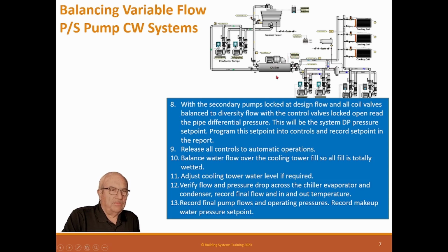And also, more than likely, you're going to have to come out early on the job and set the water through the bundles, because the chiller manufacturer won't start this chiller until he's guaranteed he's got design flow through those. So you may have to set the primary pumps and condenser water pumps to get that to let him start up before you balance. So that's a primary, secondary. It's not difficult to do. It's easy to do. Critical factors are no air in the pipe, and that the decoupler is actually done correctly.